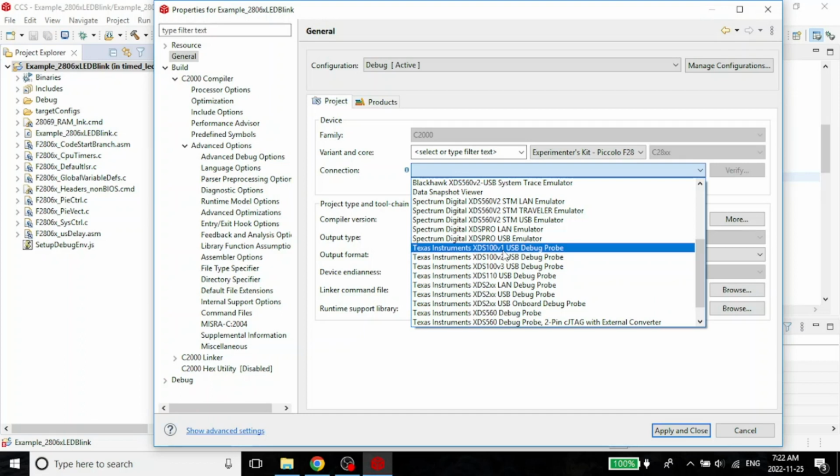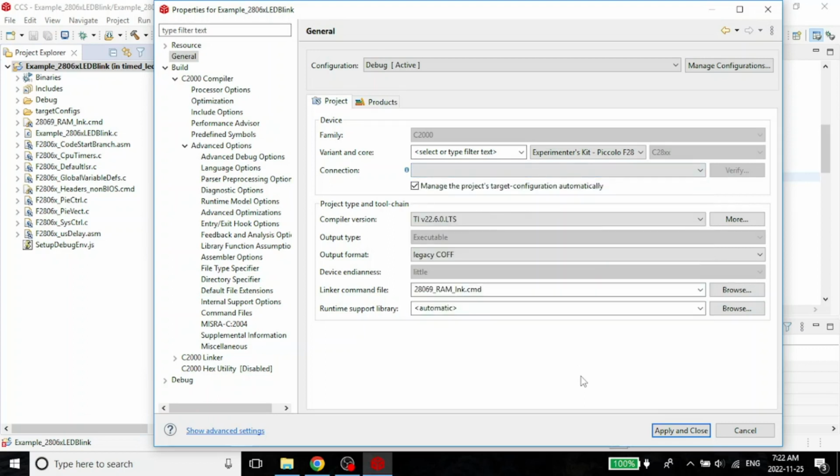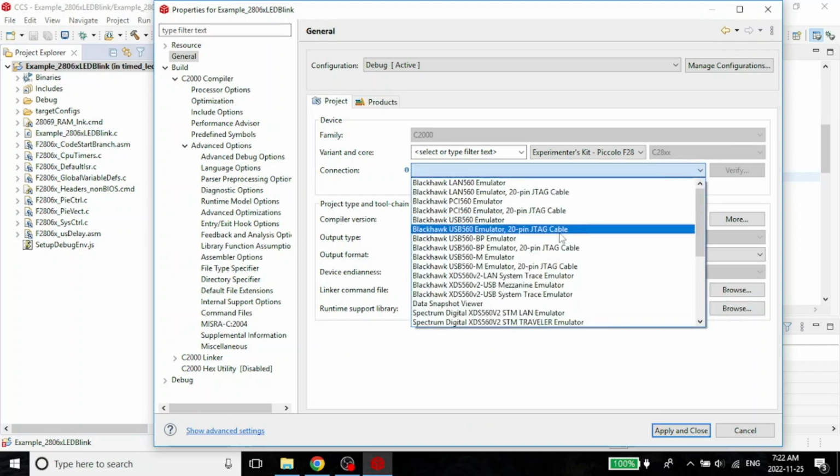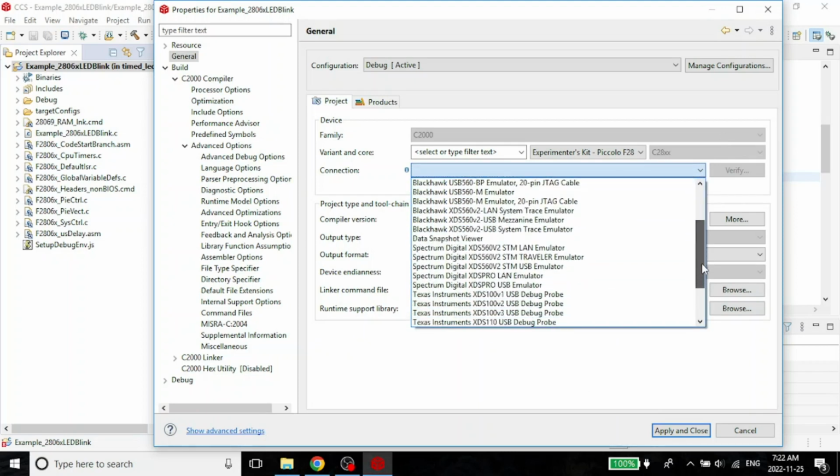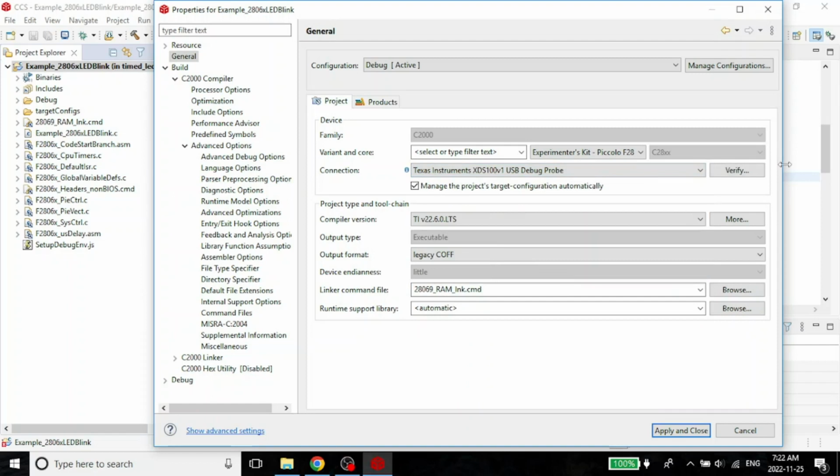That is, when you buy your kit, you open that cardboard box, you will see a glossy paper along with the CD, and that glossy paper contains that information. If you lose the glossy paper, then the best way is to choose one of these, and to make sure, for example, I'll just choose one of these and click on verify. Most important, the end result of verify should be that your JTAG connection has been successfully completed, right?